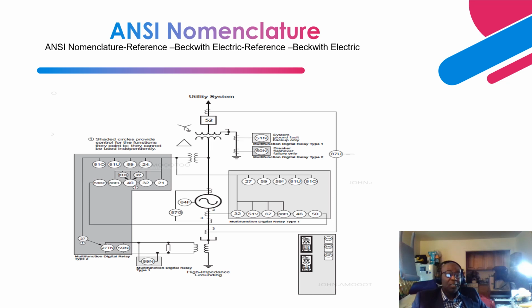For the protection scheme of this generator step-up transformer, as you can see over here, we have a 51N element and a 50N. This one is an instantaneous neutral overcurrent protection, and this one is a time neutral overcurrent. This acts instantaneously, and this one operates based on an inverse curve.